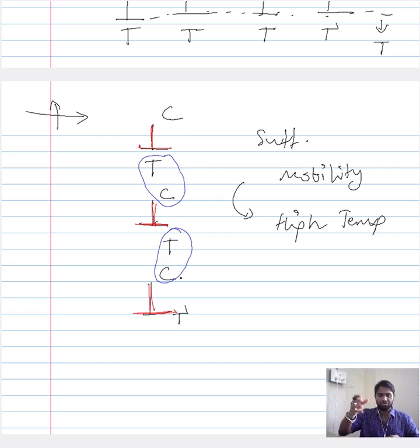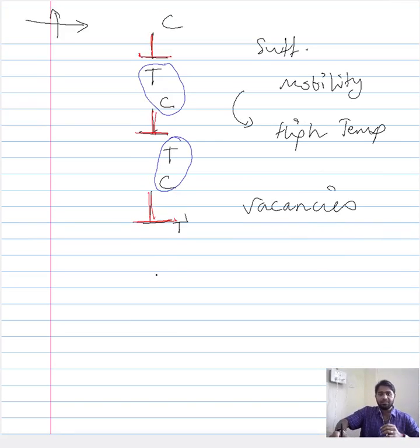In order to establish a pile up like this in the vertical direction, the dislocation needs to climb one over the other. This climb requires a sufficient amount of vacancies, and we have seen that the concentration of vacancies with respect to the overall concentration also increases with temperature.